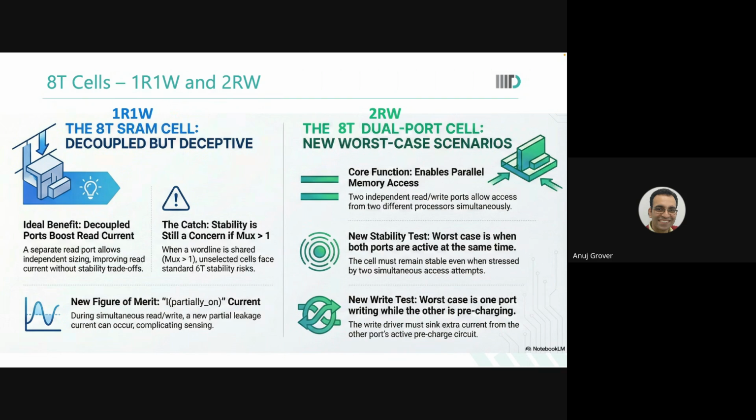That's a huge burden, an overhead, not just in terms of hardware, but also in terms of cycles in which coherence checks are being done. There are halt states that can appear in the processor. If you have a dual port memory, on the other hand, those halt states and those synchronizations are no longer required. So there is an advantage of using a dual port memory.